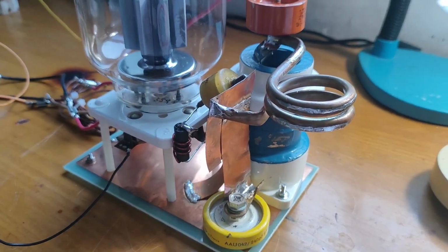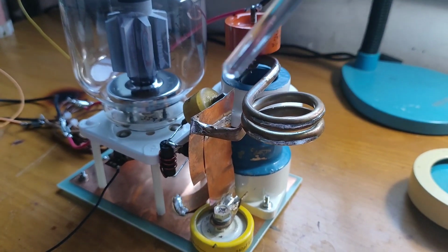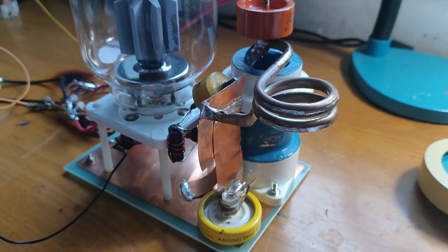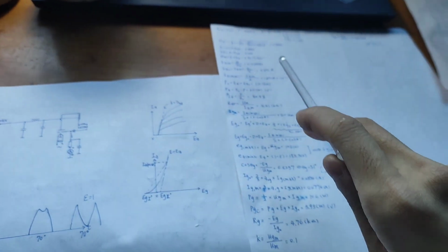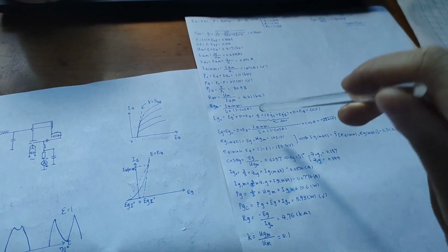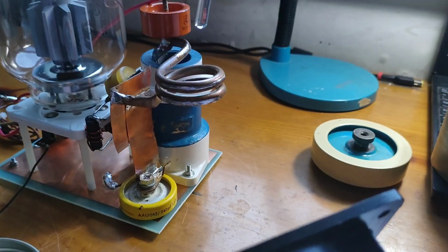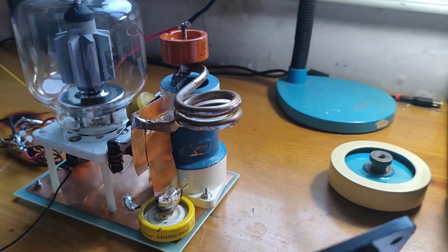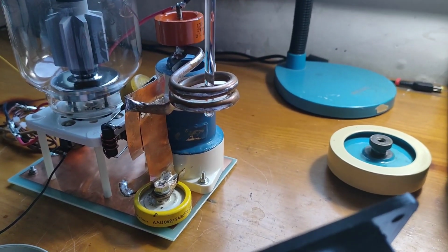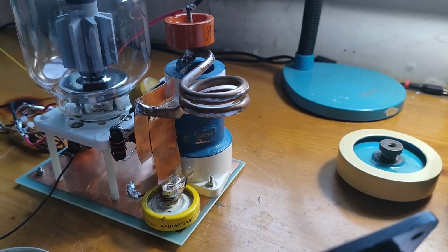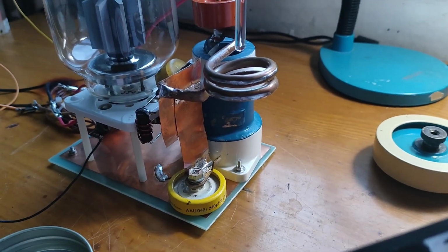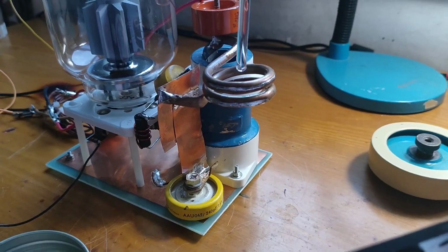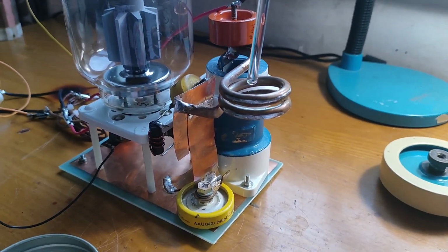So that's all about how to get the oscillation started, and then how to tune your oscillator. You need to have some load inside this coil to get the working condition to your calculated values. You need to get a load for it. So you can simply use some iron, which can be inserted into the resonant coil. Here, I use some iron in it. What I use, you will see very quickly. And when you slightly insert the iron into your coil, the first thing you need to check is your cathode current.